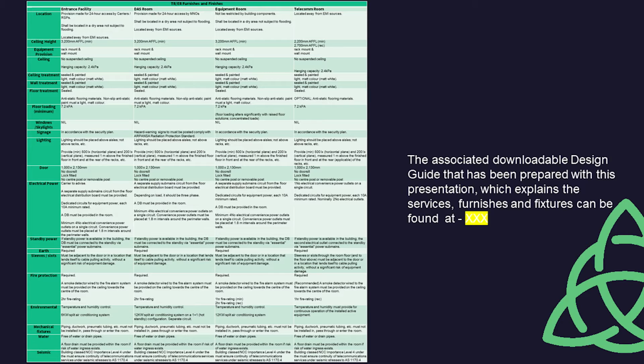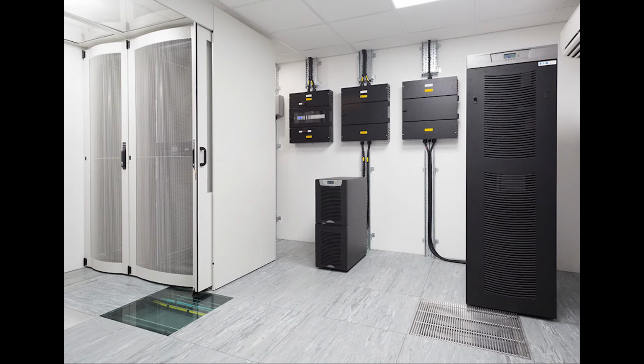The Mobile Network Operator's DAS room is another separate equipment room that is now becoming a standard space in all large facilities and high-density buildings over approximately 10 stories. The DAS room size and requirements are stated in Section 8 of the Australian Mobile Carriers Forum Design Specification for Distributed Antenna Systems. Some tips are: